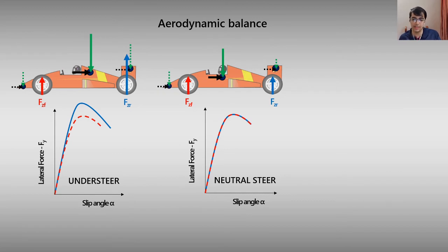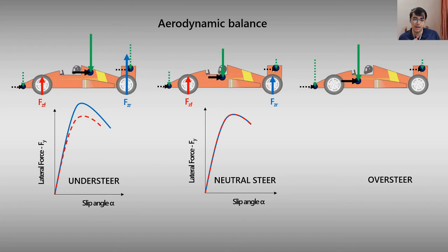Another way to look at this is if there's more load on the rear tires, like there's more aerodynamic load. Important to understand the difference. If there's inertial load, if there's inertial mass at the rear of the vehicle, it actually causes oversteer. Again, we won't get to the details of that because that has more influence in terms of lateral dynamics. But in this case, because there's more air, there's more downforce at the rear, the car gets pivoted at the rear. So when you have a pivot at the rear, the rear is planted and the front is not.